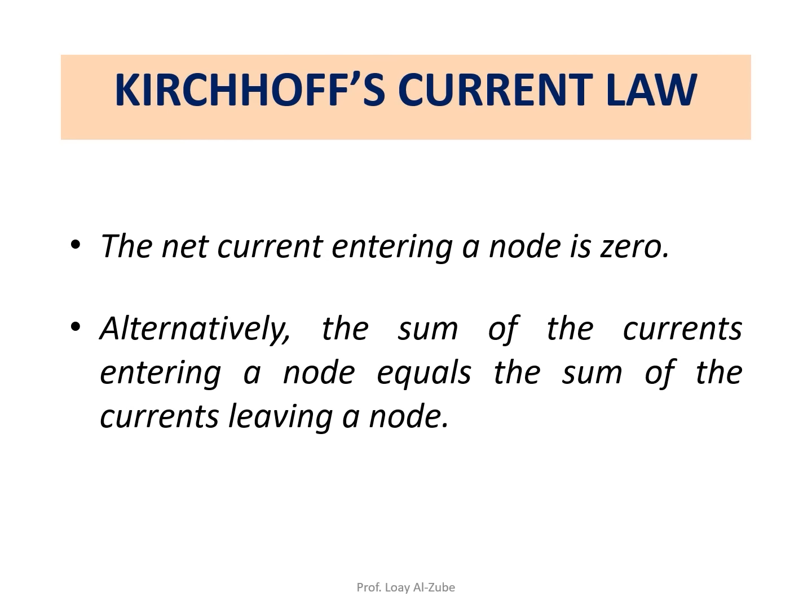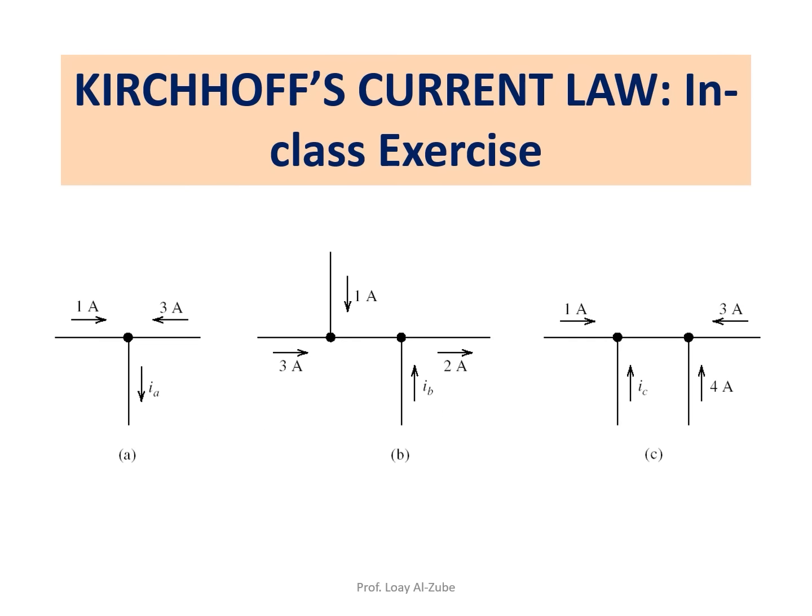Remember, either the net current entering should be equal to zero, which means you need to be able to put positive and negative, or you look at the sums. So let's do the first one. This is a node, right? That's the point where all the currents are getting in or out. I always use the simplest one. I will say everything that comes in should equal what's coming out. You need to put a notation, positive or negative, if you want to do this. I will say that coming in is positive and getting out is negative. So the summation of all these currents should equal zero, right?